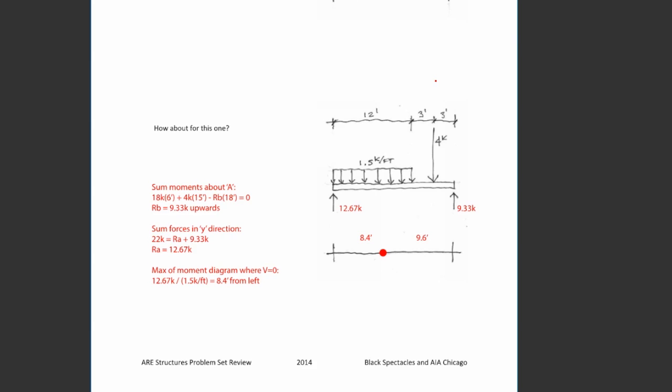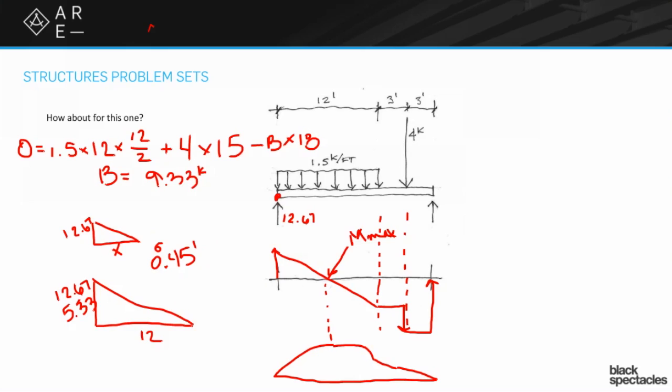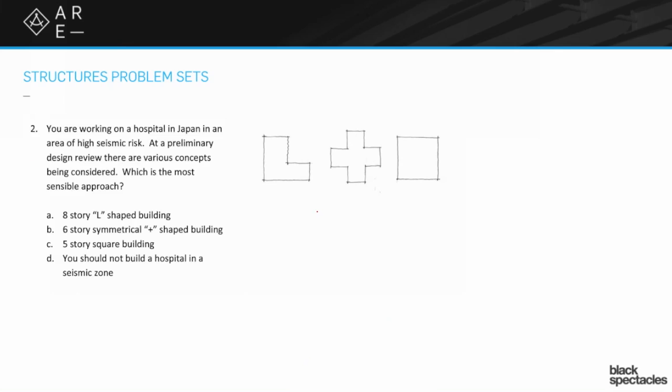Again, this is one of those things where you don't necessarily need to do the moment diagram in order to understand where the maximum moment is, as long as you understand the relationship between the moment diagram and the shear diagram, which obviously is also related to the loading diagram. Okay, way to go, Spencer. All right, going on to problem number 2.